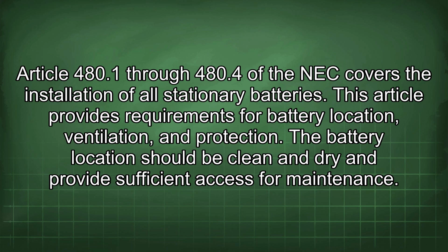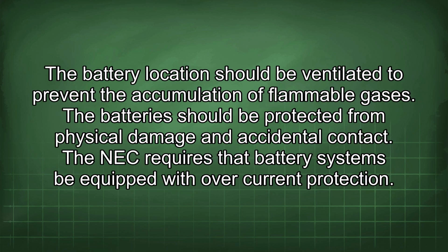The battery location should be clean and dry and provide sufficient access for maintenance. The battery location should be ventilated to prevent the accumulation of flammable gases. The battery should be protected from physical damage and accidental contact.